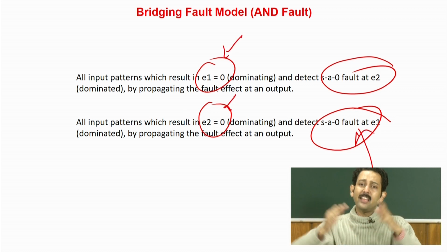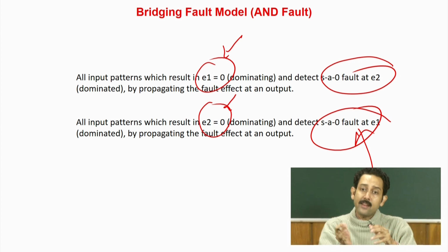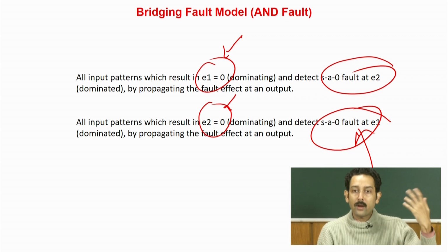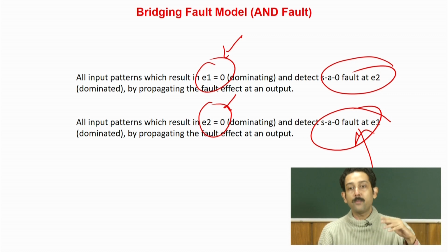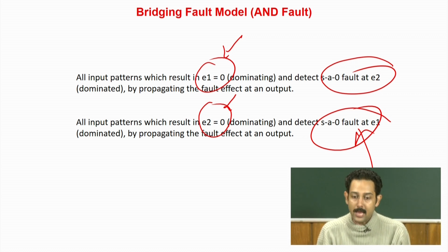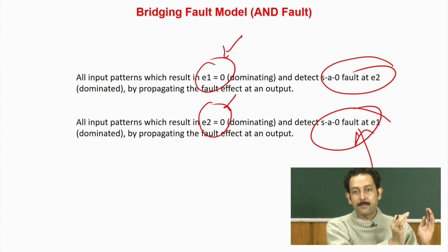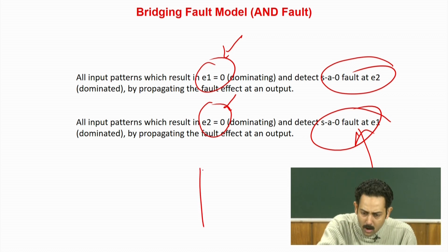If the circuit is very big, you can understand that even adding one more complexity will lead to more time and more iterations, because it is not about just setting another constraint. Setting another constraint means you may have to reiterate, because you may start having conflicts. The more constraints you put, the more conflicts you will have, and more iterations of the test pattern generation rounds have to be there. So people try to restrict their bridging fault models to a small part of the circuit.